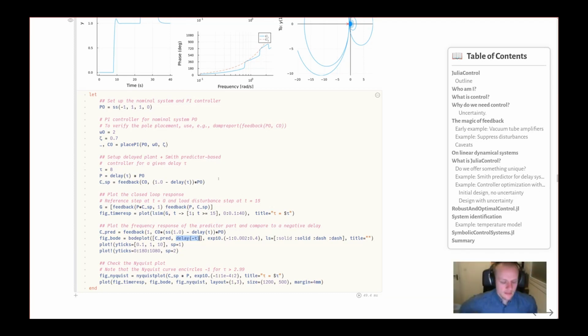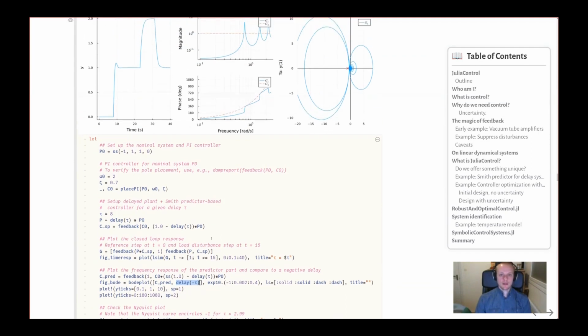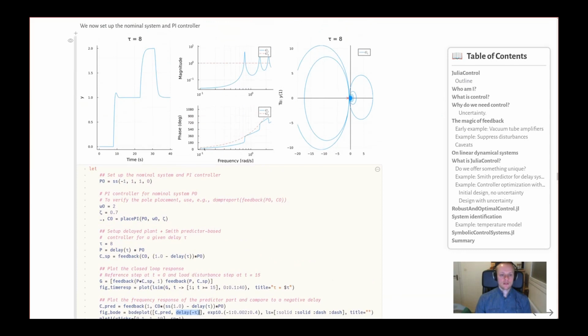So most of the time we can't see into the future. Sometimes maybe we can because we know how signals would change in the future. But we might as well compare the response of our Smith predictor to this ideal predictor. And we see that the ideal predictor has a unit gain, flat, whereas our Smith predictor has kind of a jagged gain like this. And the ideal predictor has an increasing phase like this, whereas our actual predictor has kind of this interesting phase curve here.